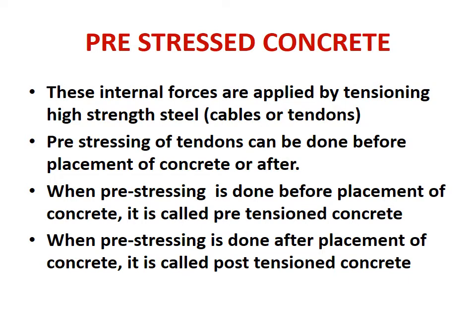Now these internal forces we are talking about are applied by tensioning high strength steel, normally called cables or tendons, and pre-stressing of tendons can be done before placement of concrete or after.